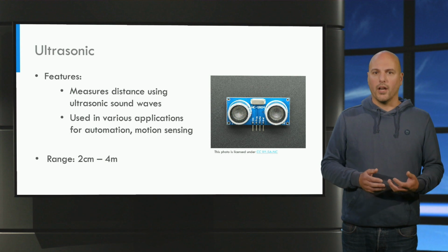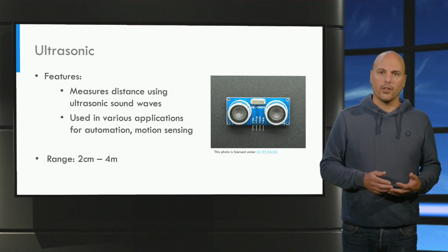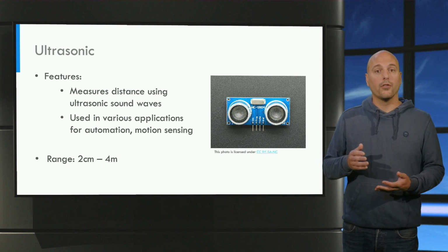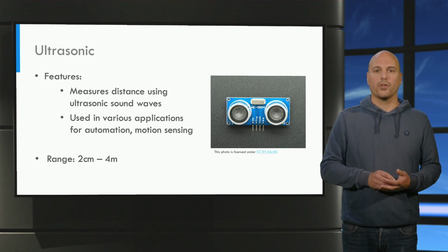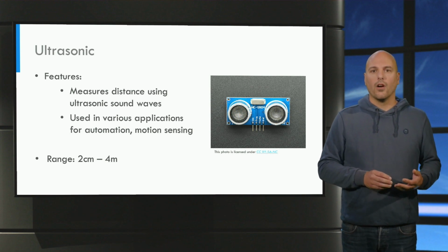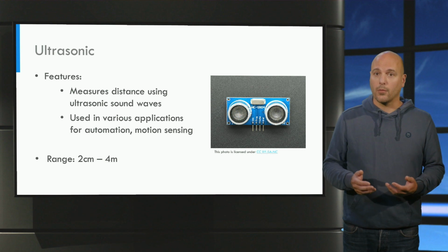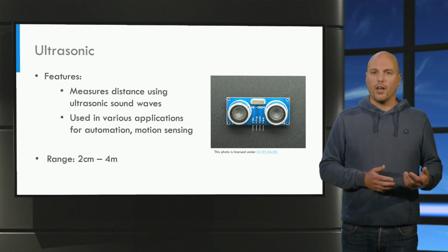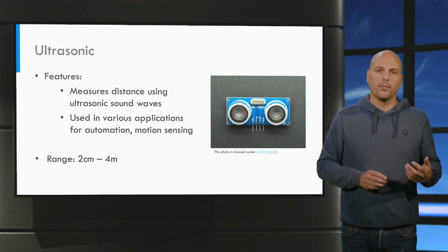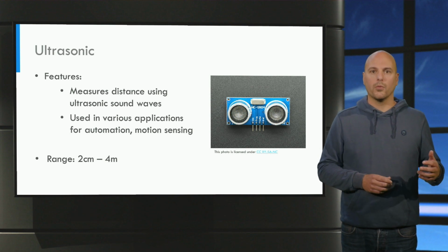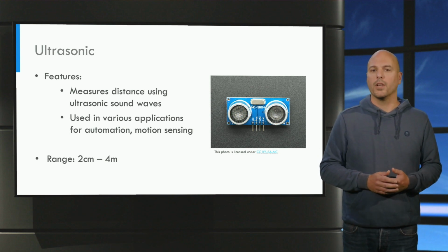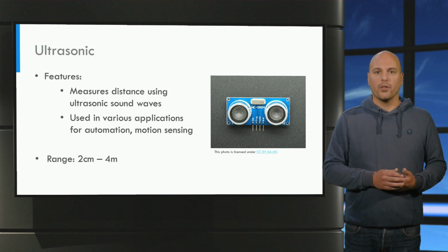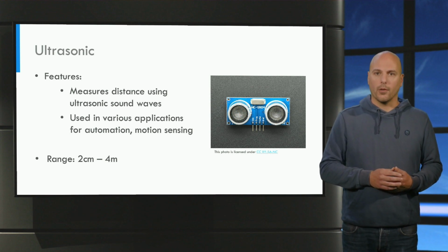Instead of sending out a light beam, the ultrasonic distance sensor sends out an ultrasonic sound and waits for the return pulse. Also with the goal to detect the distance of objects. Other than the LiDAR, this sound produces a wave and therefore will detect any object within this beam, called the field of view. It will therefore not know the direction of the object.